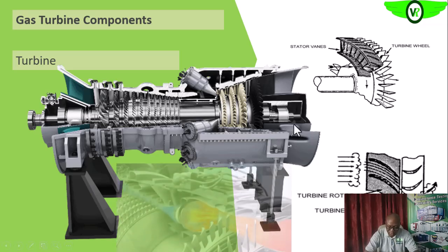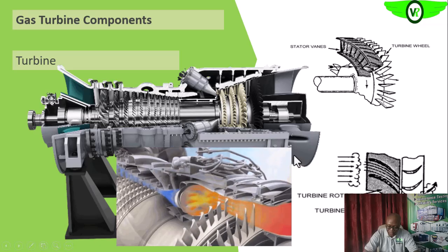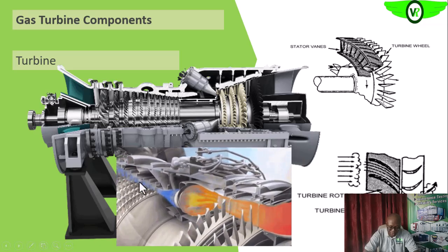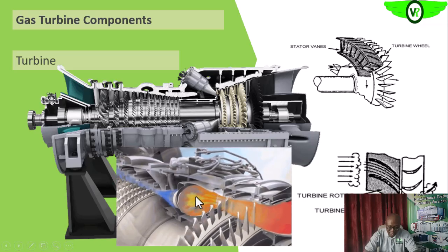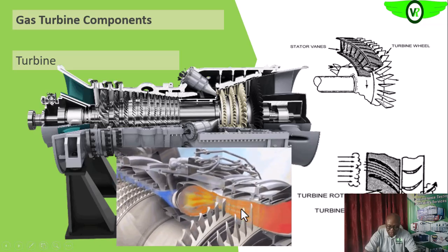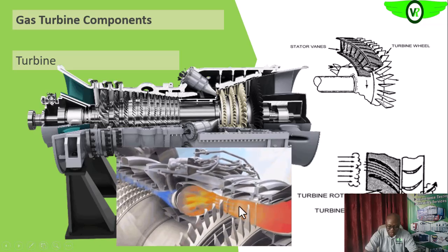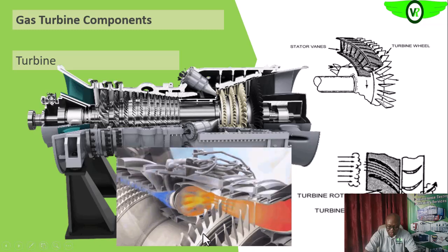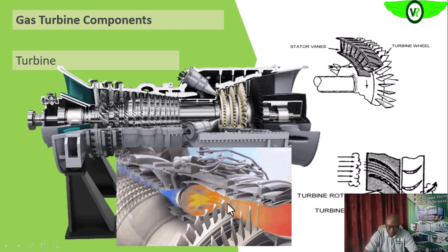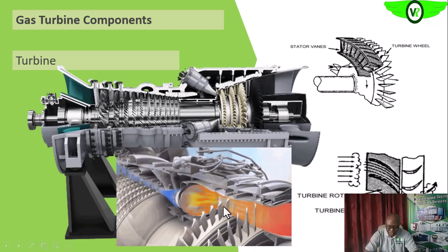So simply put, that is how the gas turbine works, and that is what you are seeing here. The intake air is compressed, sent to the combustor, ignited, and the hot combustion product flows through the turbine section, causing the rotor to turn since the fast moving combustion product molecules are impinging or striking on all of these blades.